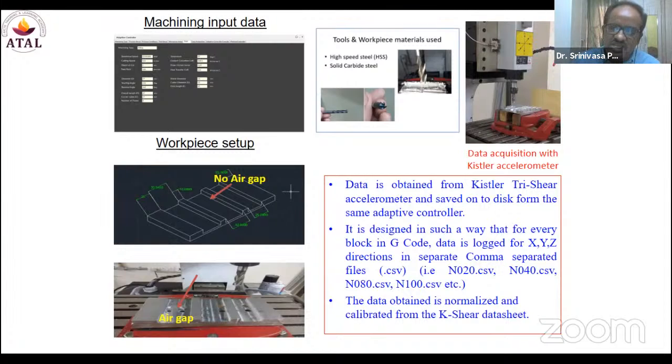If the vibration levels are very much less, it will increase the feed to double, triple or 4 times the programmed feed rate. If I have used a feed rate of 40 as the initial value, and vibrations are not found as the cutting tool travels from one end to another, then my system automatically suggests, because the vibration levels are less than 1 or less than 2 or some cutoff value, it will automatically double the feed rate value.